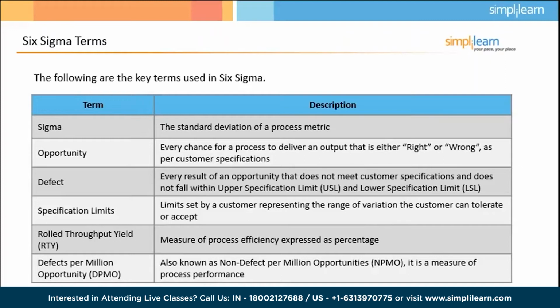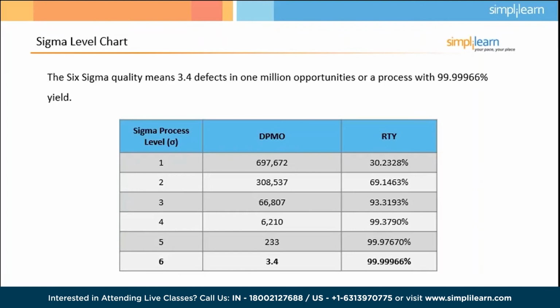Now, I mentioned earlier on that, at the Six Sigma level, we're 99.9996% good. Another way to look at that is defects per million opportunities. At the Six Sigma level, we'd only produce about 3.4 defects. Now, that sounds really good. In fact, if I said I was 99.379% good, most people would be pretty happy with that. I think most people would be pretty excited. They'd be putting up banners that, hey, I'm 99.379%. But for every million opportunities for a defect, they'd produce 6,200. Anybody want to get on a plane that's at 4 sigma?